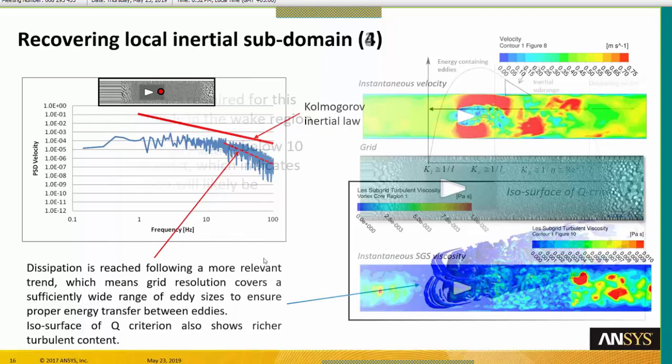So remember, this constraint is only for the LES and for aerodynamics. When you do aeroacoustics, it will be much more difficult to respect this constraint of Courant number. And we are talking, in fact, about an acoustic Courant number. So here the constraint for the aerodynamics is below 1 for this ratio U delta T over delta X.